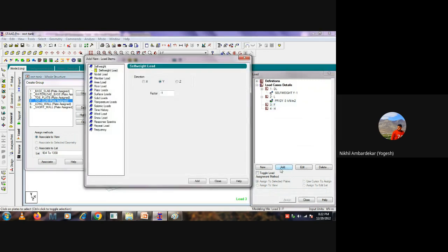Okay, now fluid load. We want to add fluid load. So what is the intensity of the pressure? 5 meter was the internal water height. So just go with only the test condition. The tank is fully filled. Okay, 5 meter means 50 kilonewton per meter, which is a triangular force.